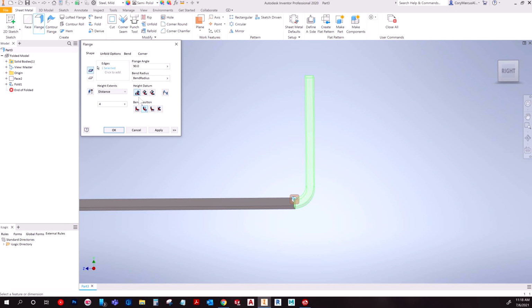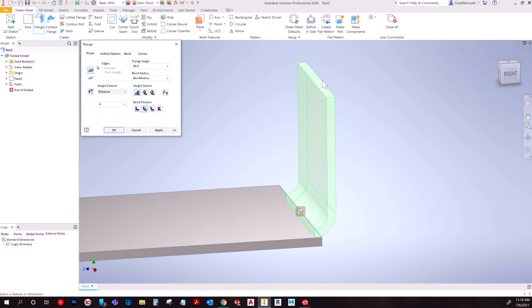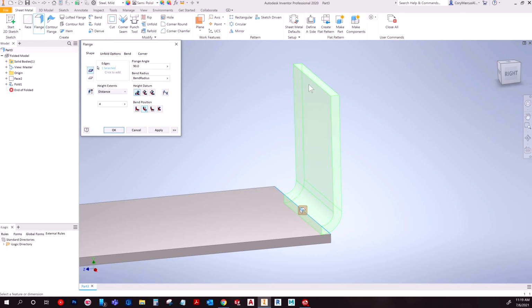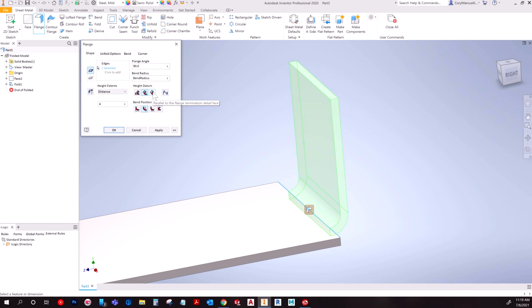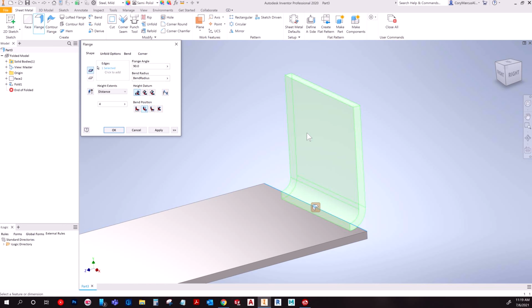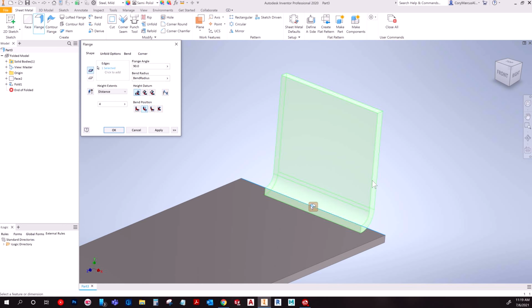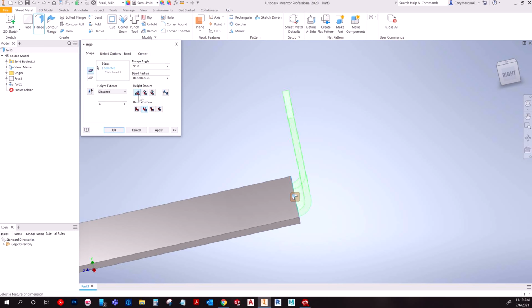From this one, it's bend from the intersection of the 2 outer faces. I'm assuming this is one of those I'd have to actually get measurements on to confirm, but I'm assuming it's this face to maybe this other face over here. Usually you end up having to toggle these around, and it's a lot easier when you have more definition to tell what you're working with. But you can easily have one of these 3 wrong or one of these 4.